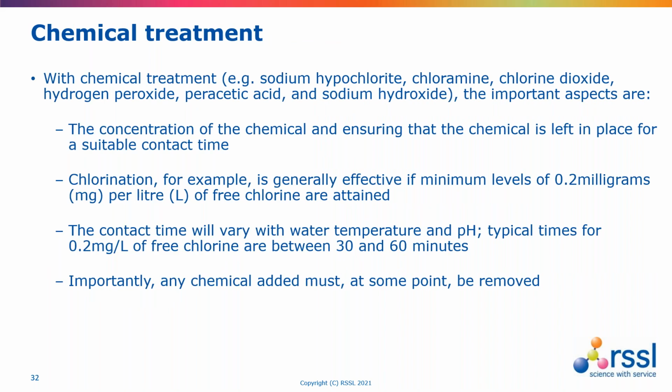With chemical treatments, there tends to be a division into the chlorine-based ones, so sodium hypochlorite, chloramine and chlorine dioxide, and then the peroxygens like hydrogen peroxide and peracetic acid on the other side.